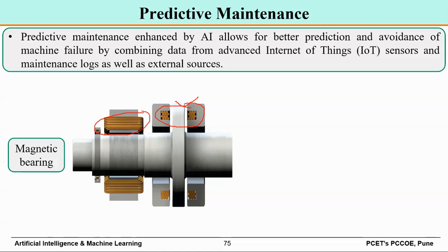So we discussed in the decision tree how to split the data, right? For axial movement, a cutoff is set. For example, if the axial movement is beyond, let's say, I'm assuming 20 microns, what will your system do? It will trip the compressor or stop the shaft.